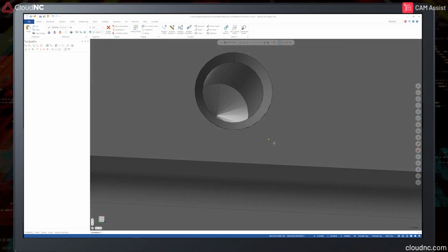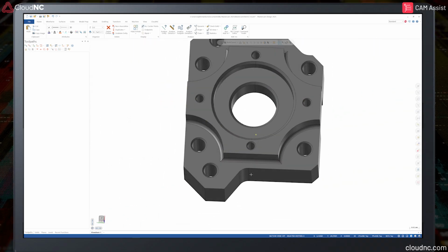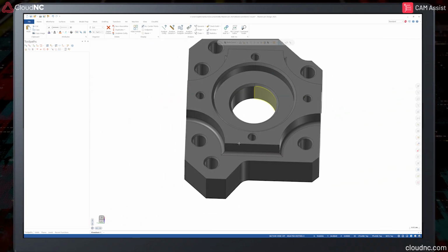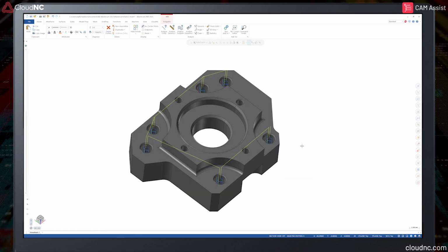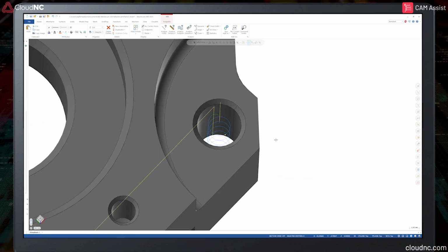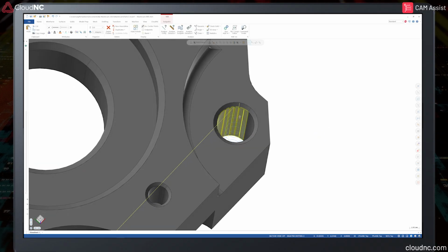On closer look at these holes, they are actually made up of split surfaces joined together. Due to this, CAM-Assist may not actually recognize these features as holes, as it technically interprets them as individual surfaces stitched together. This can prevent the intuitive selection of a drill tool to produce the hole, resulting in helical machining of the hole with an end mill instead.